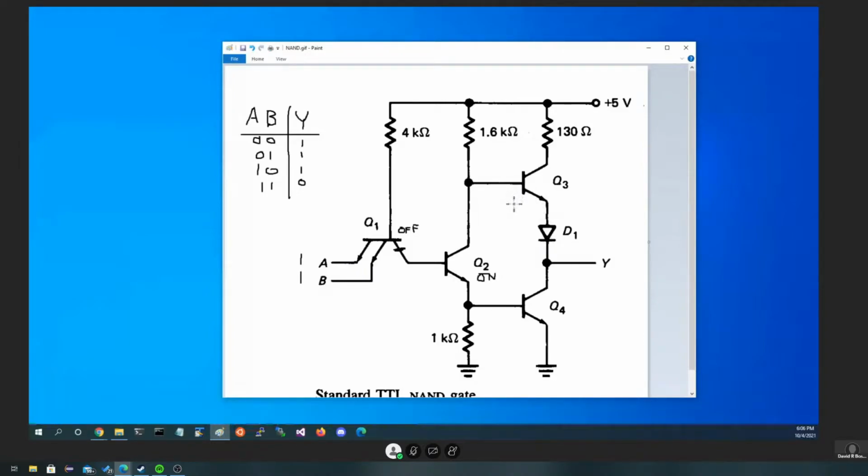And what we would expect is, in this case right now, for this transistor to be off. We don't have sufficient voltage at this point to turn this on, which means nothing is going to be coming out of the pin. Instead, this guy, who, if you look at the 5 volts, has been divided into 1.6K, 1K, a voltage which is going to be high enough that the base will be able to be 0.7 volts, turning this transistor on.